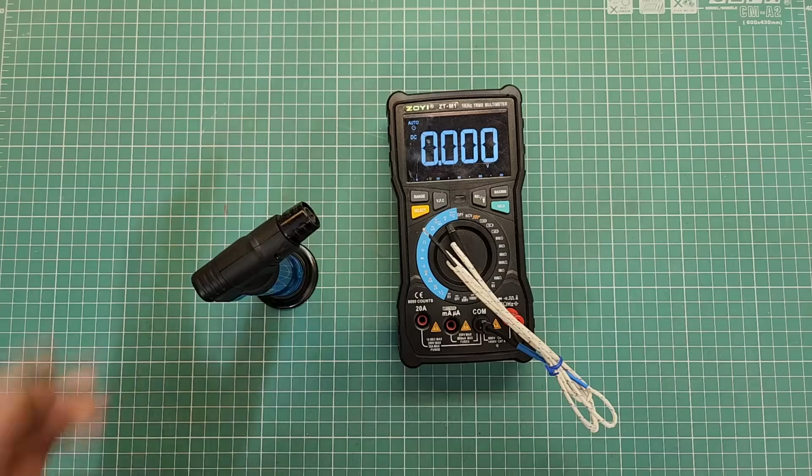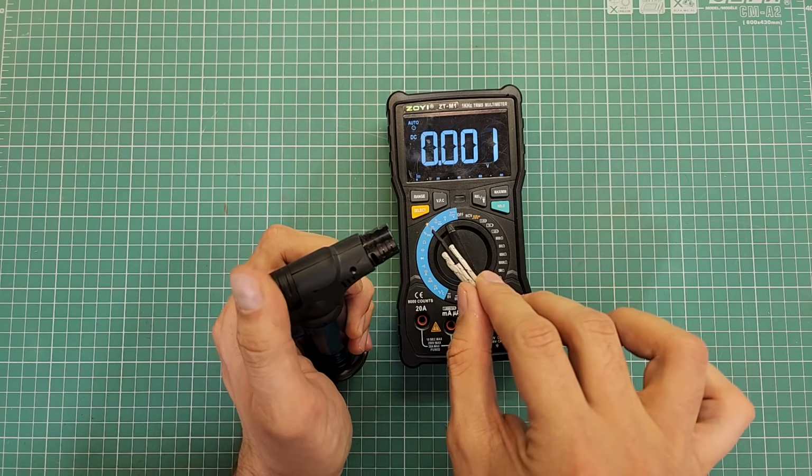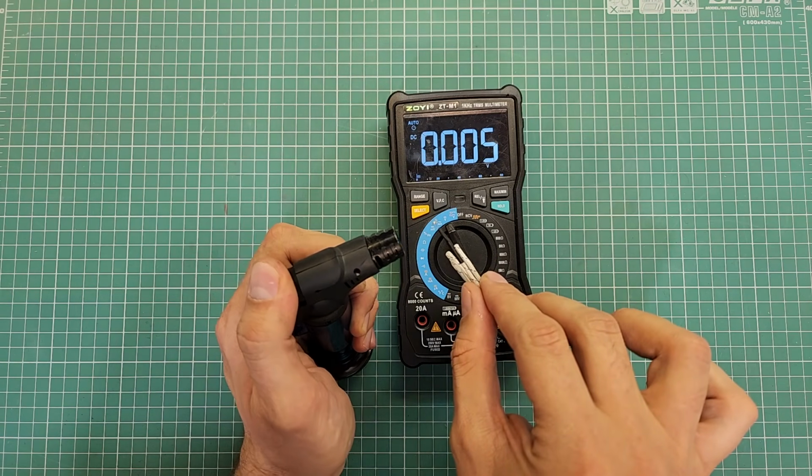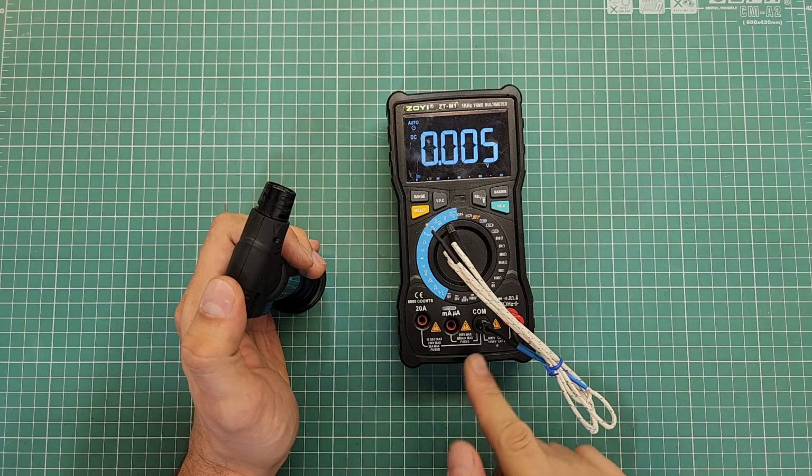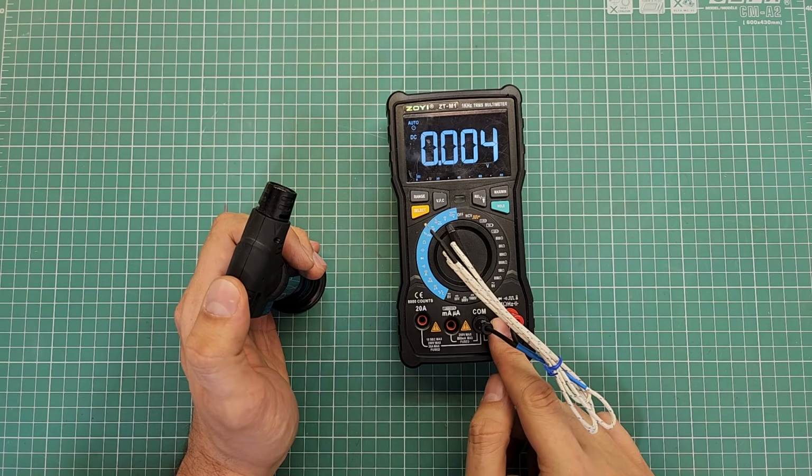The problem is that the voltage between its leads is so tiny, it's impossible to read it directly using ADC unit in microcontrollers. We have to amplify that. Since we have two leads here, the best option is to connect negatively to ground and positively to a non-inverting amplifier.